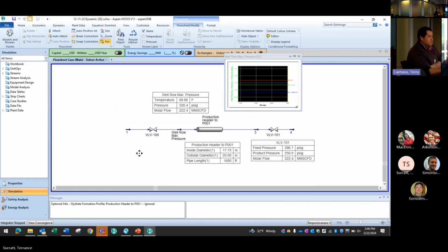So one of the interesting things about a simulation is you can simplify it so long as the assumptions you make are conservative assumptions. In this case, the process itself is quite a bit more complicated than what I was looking at here. You have your different wells lined into the same header, and you could also model those valves closing over time. You have different downstream valves that could fail closed. You could look at how long it takes those to close, and that could also be incorporated in this.